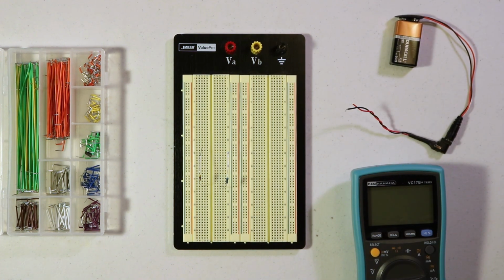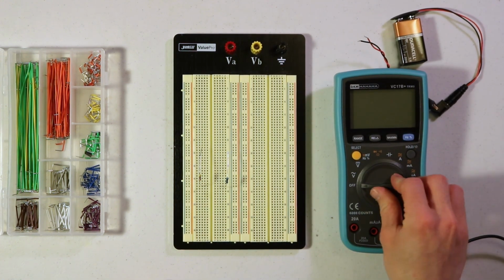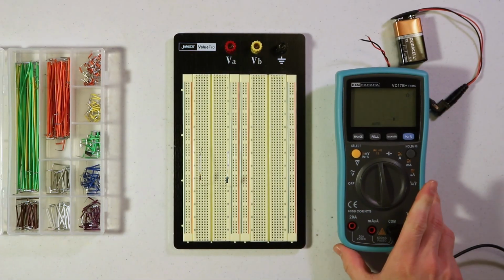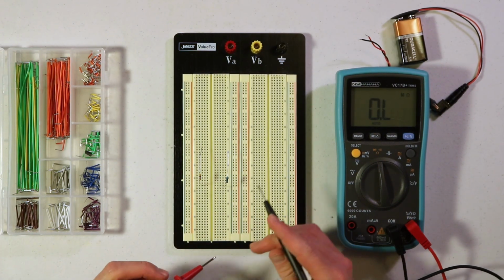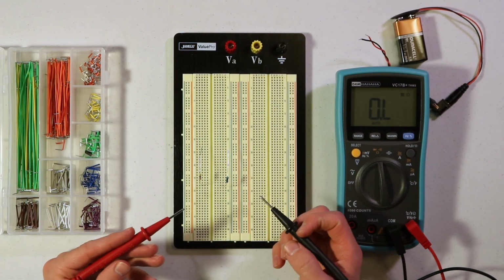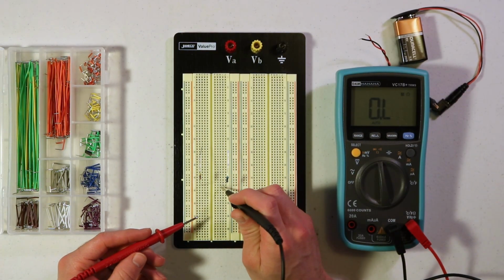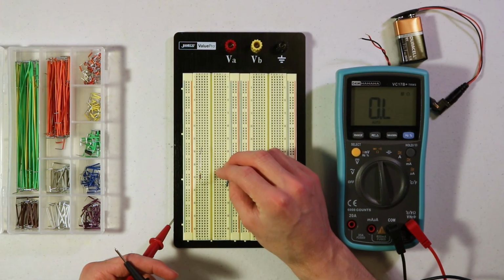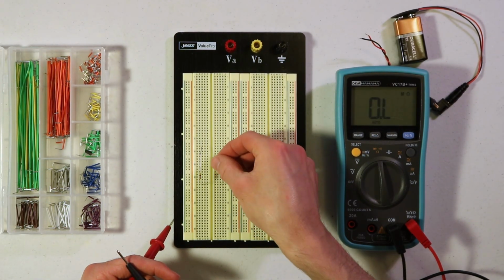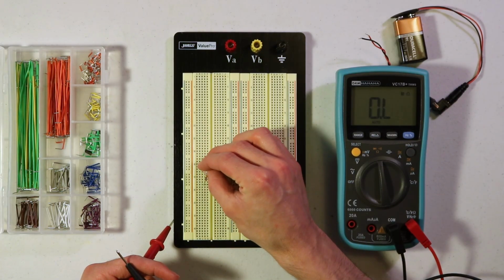First of all, we need to measure the resistance, so we'll use the multimeter and switch that to resistance. And then to measure something with the multimeter probes, what you want to do is just place them down into the little breadboard holes. So first of all, put your resistors into the holes, both ends of the resistor, and